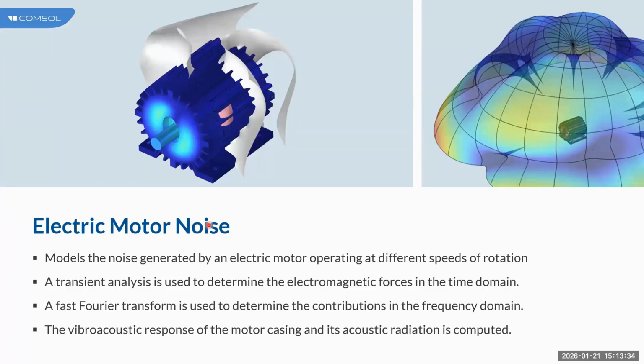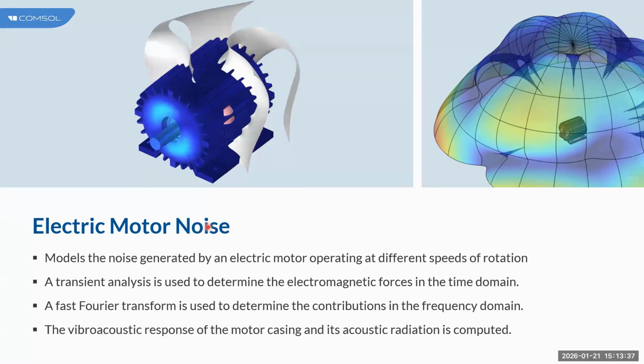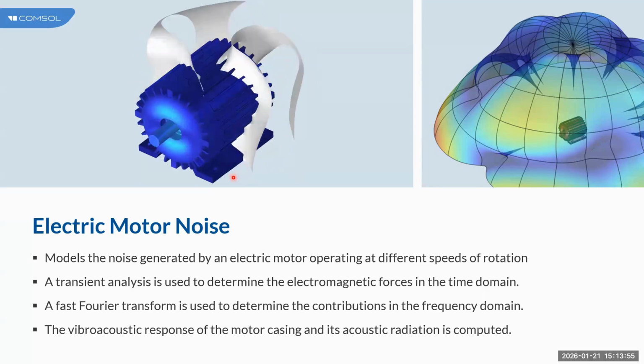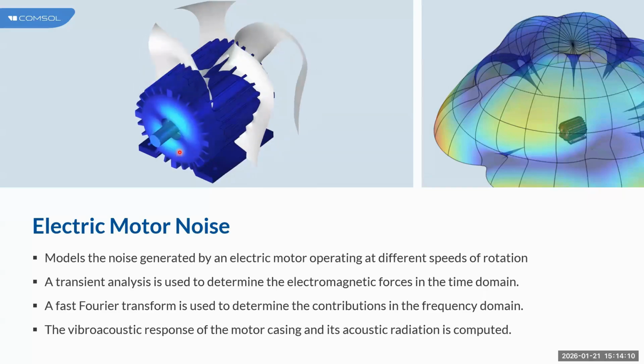So moving on, we have an example here on electric motor noise from COMSOL's application library. The sound we hear from an electric powered machine is a multiphysics phenomenon, as the motor's electromagnetic activity sends vibration through both the machine as well as the surrounding air. Through the COMSOL Multiphysics platform, you can simulate the acoustical effects generated by this permanent magnet synchronous motor, which is shown here, at different speeds of rotation.